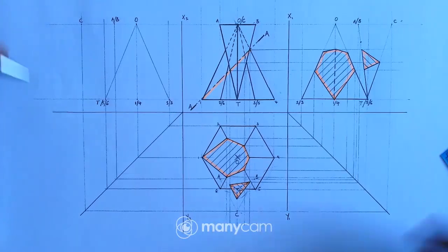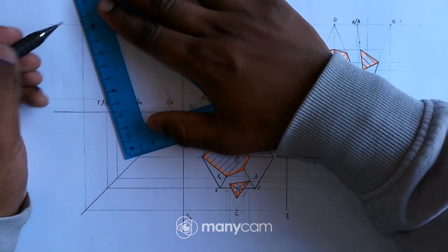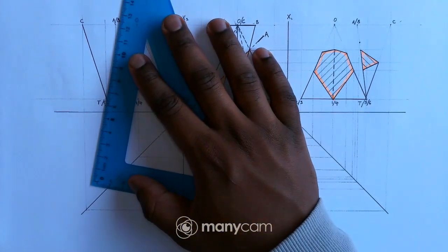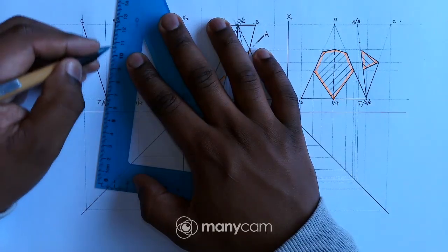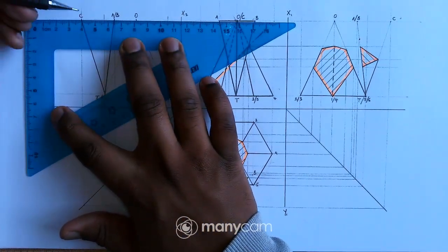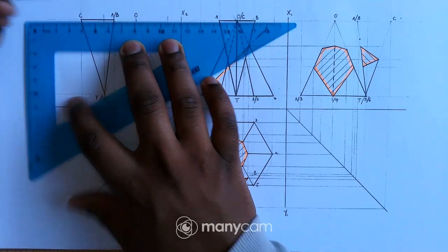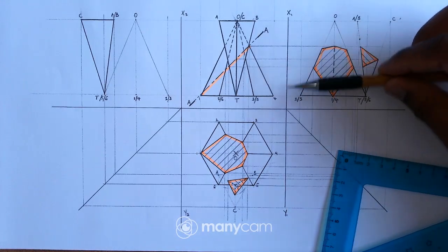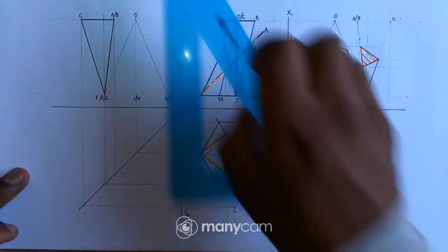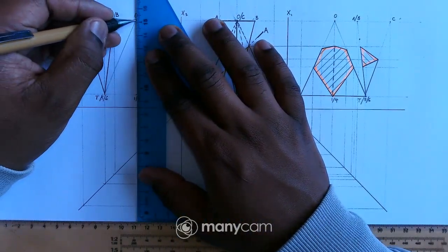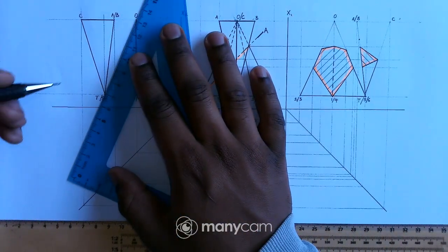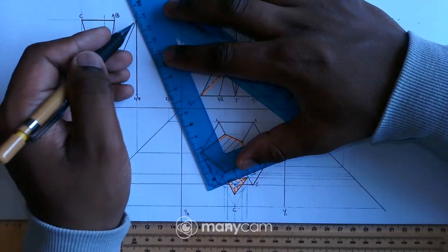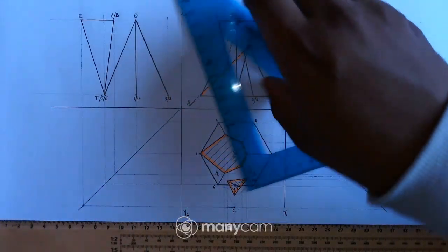I have C there, so I can just draw my right view, solid line there, solid line there, solid line up there, and then looking from this direction, obviously I'll see this edge O4, so I can just draw in that edge there, and obviously this one's O5 and O6 and O2 and O3 and the base.